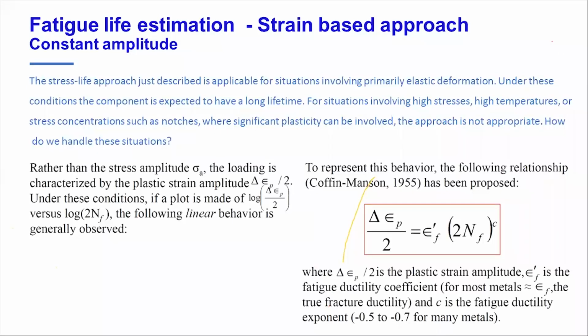So let's say truck cranking. When you start your vehicle, some component may undergo high strain, it may go into the plastic zone. But how many times will you start and turn off your vehicle? Those number of cycles may not be high, high with respect to vibration number of cycles. So though it enters the plastic zone, it may do so for, let's say, a few thousand instances, because you will turn the car on and off maybe a few thousand times, not a million or a billion times.